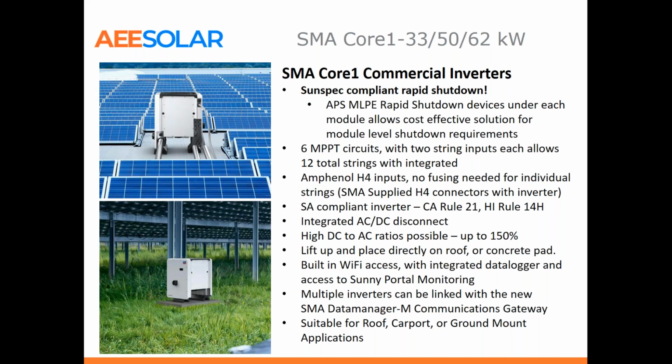Very, very nice, easy to set up inverter there. There's an integrated AC and DC disconnect, and if this inverter ever does need to be serviced, the top part just comes off, and the inverter unit can be reinstalled fairly easily if that ever becomes an issue. We mentioned high DC to AC ratios. 2 people can move this inverter around with the included handles and get it in its right spot.